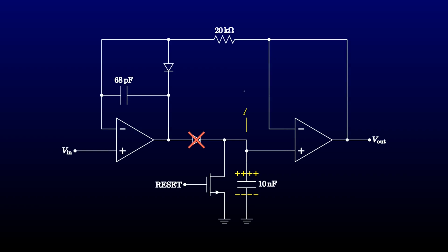I suppose the leakage path could be running to the outside world, but I'm really hoping that I won't have to go there. When that sort of thing becomes a problem, designers wind up going to ridiculous extents to fix it. Mounting components on Teflon standoffs or with flying leads to avoid current paths along the surface of a circuit board. Cleaning components aggressively with solvents and then baking to drive off volatile residues to avoid sneak paths along the component surfaces, and various other insane techniques, none of which I'm likely to be able to do on a breadboard demo. So let's just hope for the best.